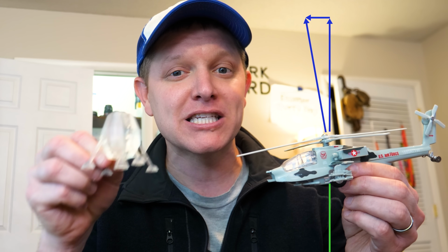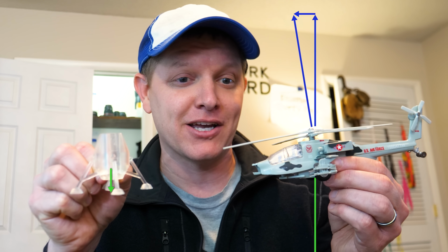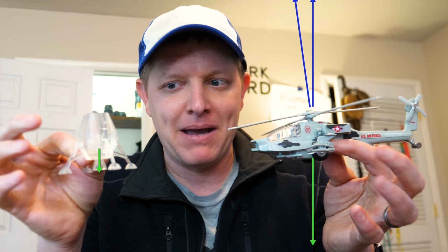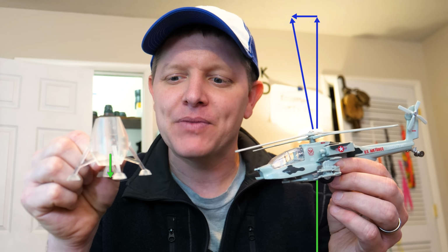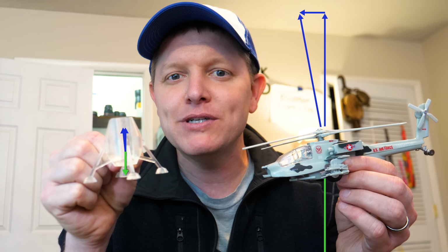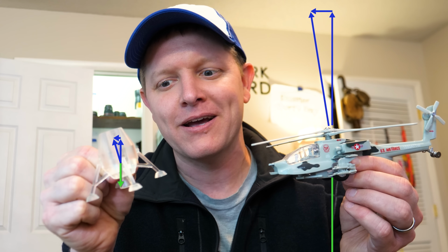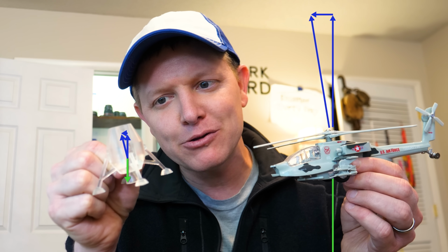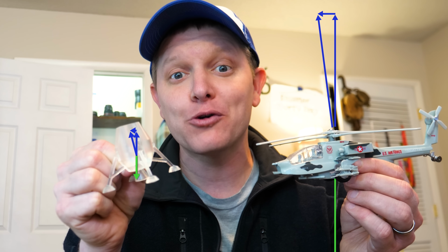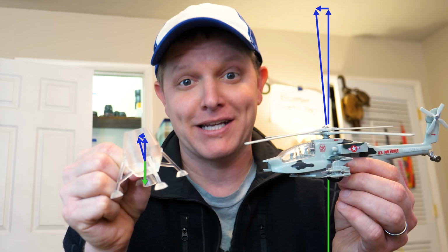Now that makes sense on Earth, but the problem is if you're in a spacecraft and your spacecraft has 1/6 the weight of a helicopter, even if they're the same mass, you have to go with me here. Think about it. If you have a very small thrust required to lift that thing, if you tilt it over and try to translate in the same acceleration moving forward, it's not going to work because as you tilt that thing forward, the horizontal component of your acceleration is far lower because you're not thrusting as much.